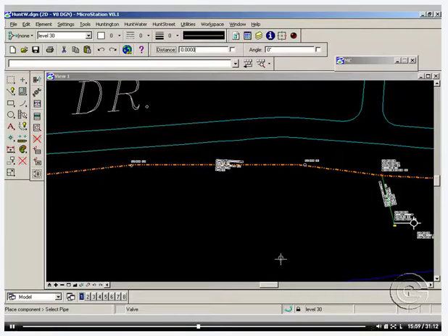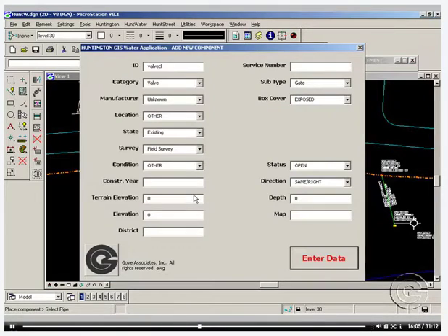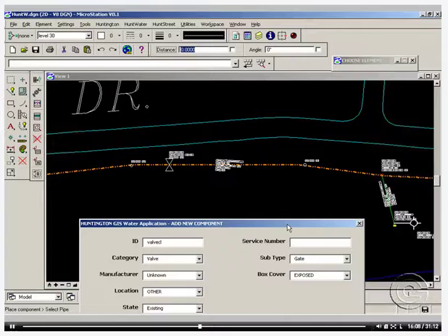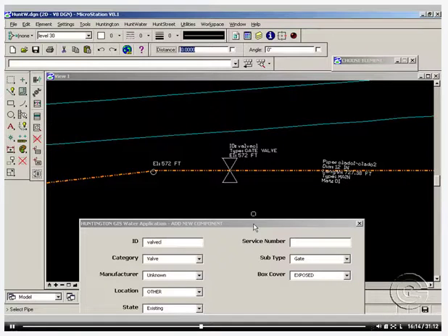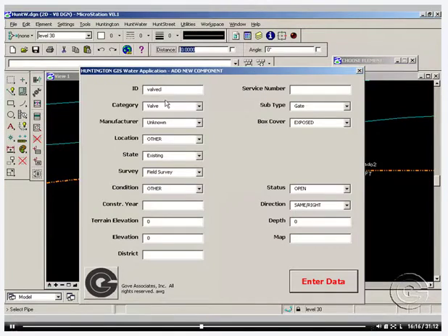We can go ahead here and hit enter, and if we wanted to place the valve on this section of the pipe, then we'll just go ahead and click on that section, accept it, and as you can see, the program would bring in a cell and place it at that section of the pipe and give us the elevation of that specific valve.